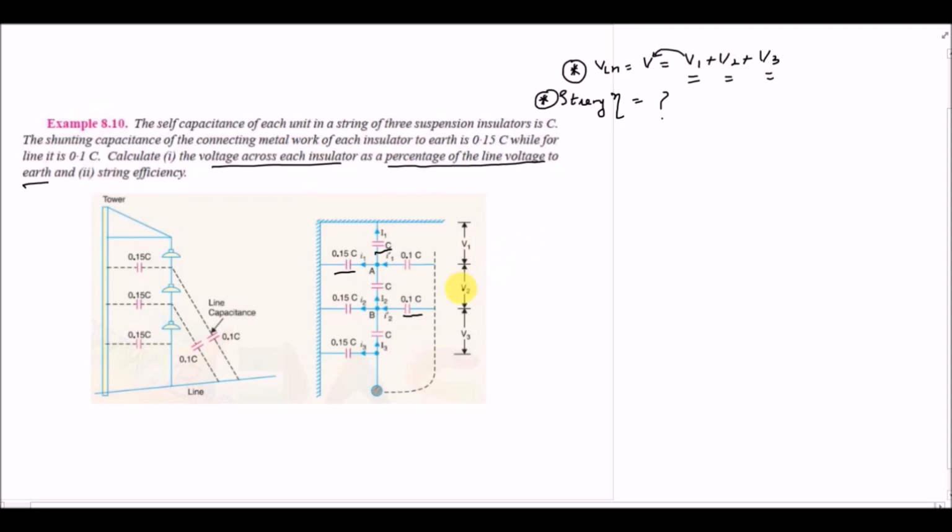So again, we will start by applying the KCL at these two nodes. So starting from KCL at node A. So now we have four currents, I1 capital and small I1, they are moving away from the node. Then capital I2 and small I1 dash, that is moving towards the node A. So the equation will become I2 plus I1 dash is equal to I1 plus small I1.